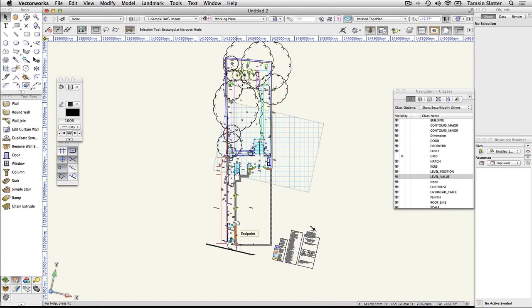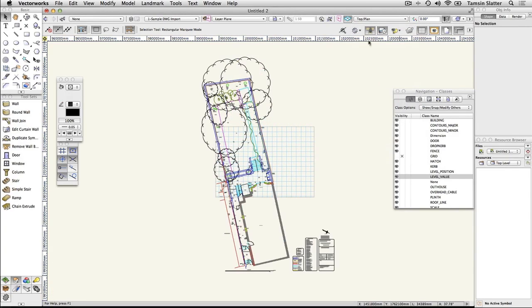Tools such as the rectangle tool, wall tool, and so forth will now easily snap horizontally and vertically and line up with the house, if that's desirable for your design process. To return to the top plan view, use the View menu on the view bar and choose Top Plan. Save your file if you wish, using File, Save. We won't be using it again as it's a standalone example designed to teach you this process alone.